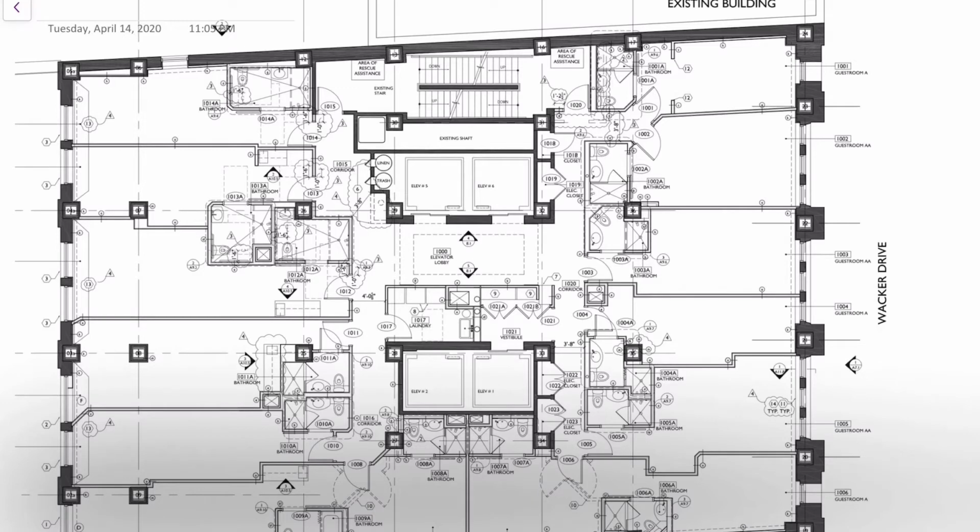And so it's an existing building, and if we take a look at this building in regards to the fire resistance and the assemblies, if we look at the exterior wall, this building has an exterior bearing wall that's 4 wythes thick of brick. And so that's going to equal at least 4 hours of fire resistance, and that's what the code requires. So this section here is 4 wythes thick, and it would be a 4-hour wall, which is what's required, which is cool.